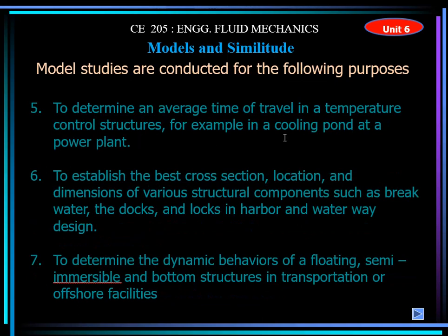Also to determine the average time of travel in a temperature control structure. For example, in a power plant, when the water goes inside to cool the heat, transferring the heat from one point to another point, that study can be done on the model also. And also to design the best, economical cross section of any hydraulic structure, we can apply this model and similitude study.